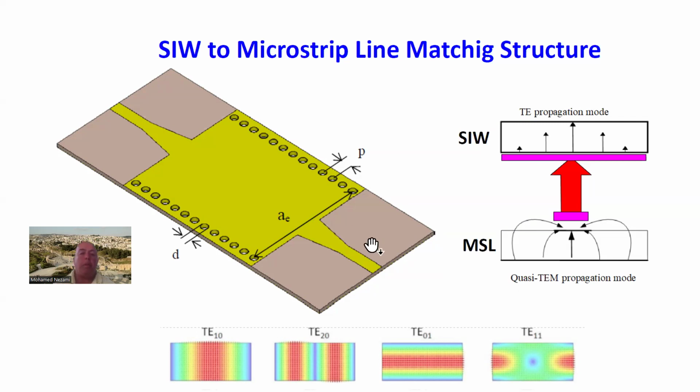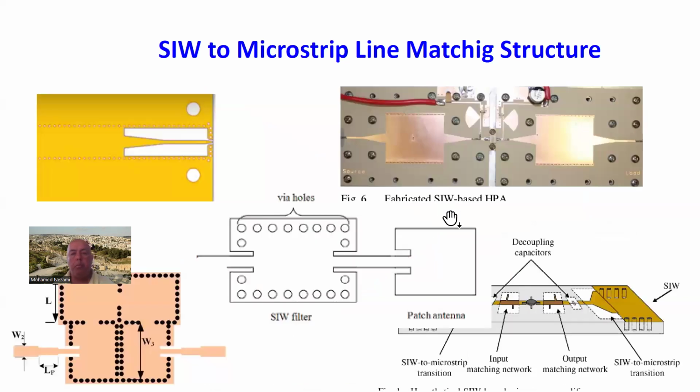However, if you really want to optimize this, we have to look at this in terms of taper line matching, which is a whole area that we want to cover. I have a whole session coming up on how, in general, to do taper line impedance matching between 50 ohm and a different impedance, or between input and output impedances.